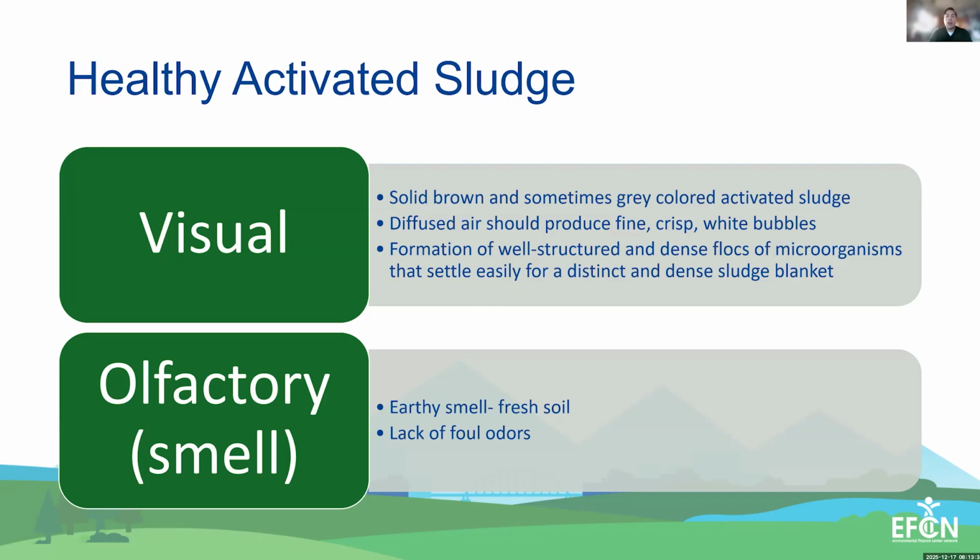Then activated sludge also has some distinct smells to it. And this tends to be an earthy, fresh soil smell, like fresh dirt or soil when it rains. Good, healthy activated sludge and an activated sludge treatment process that's running correctly should smell like that.